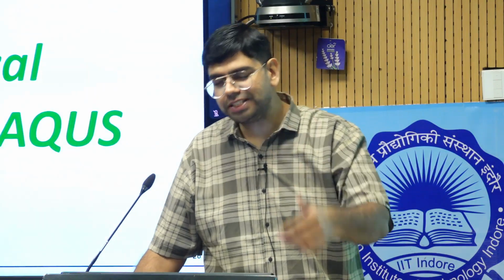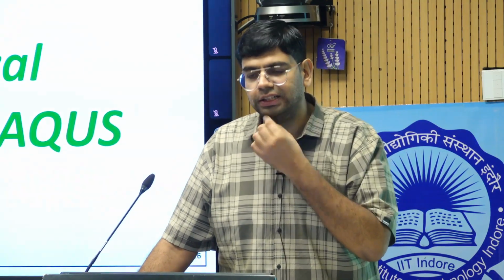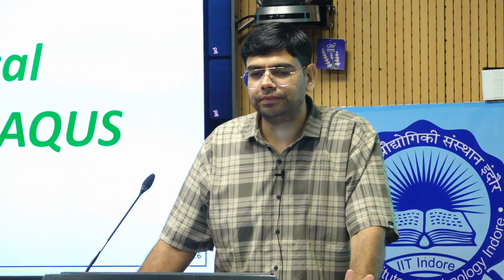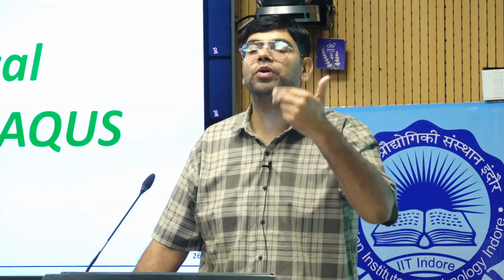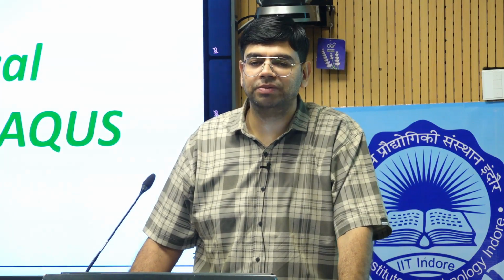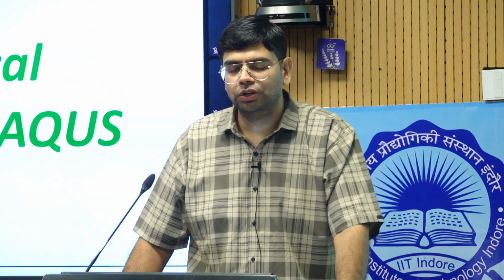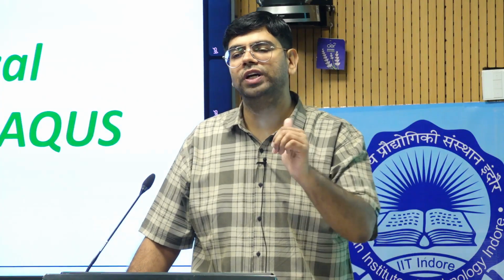Okay. We have followed similar steps in Abaqus software. But there is one catch here, as he is asking. There is no direct electromechanical coupling in the Abaqus software. Electromechanical coupling means, we already know that when we apply the potential difference, ultimately we are providing the electrostatic force of attraction. That will compress the membrane in the thickness direction and expand in the areal direction. So in order to define that, in Abaqus we have developed a user-defined element.